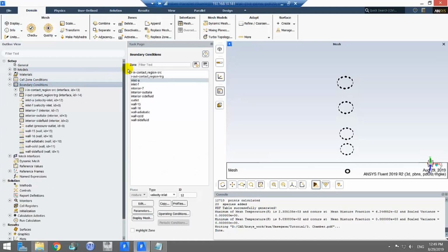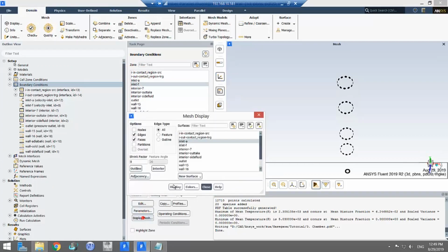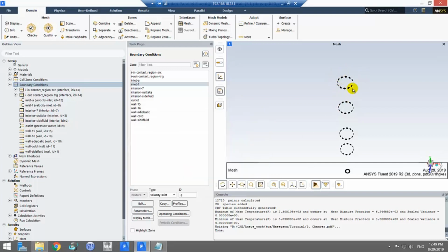In boundaries, you can see two types of inlets, for air and for fuel, and here in graphic window represented an air inlet configuration. You can see several perpendicular sections along the chamber and one swirled inlet in the bottom. Here is a fuel inlet configuration. Let's set up mass flows, temperatures and composition for both inlets.